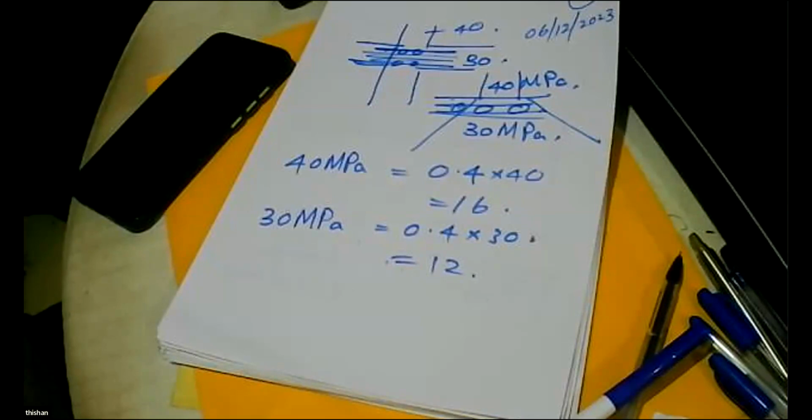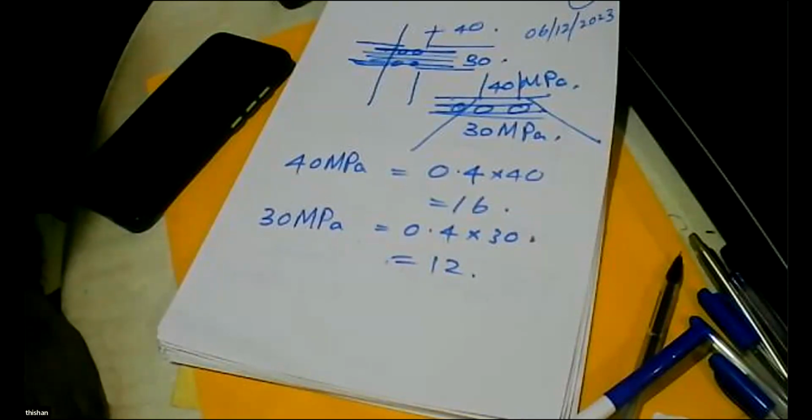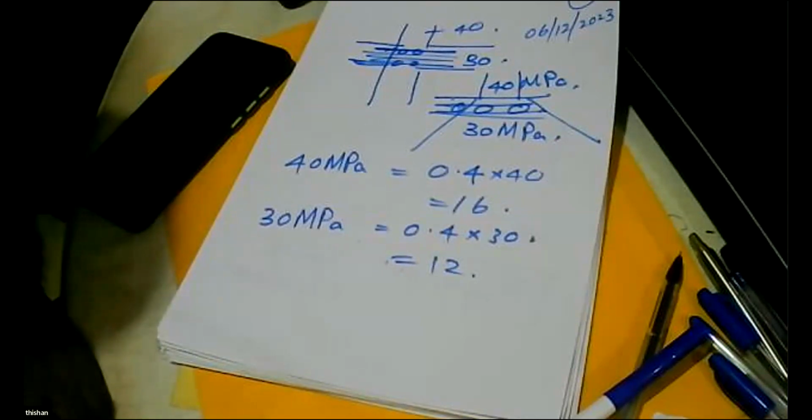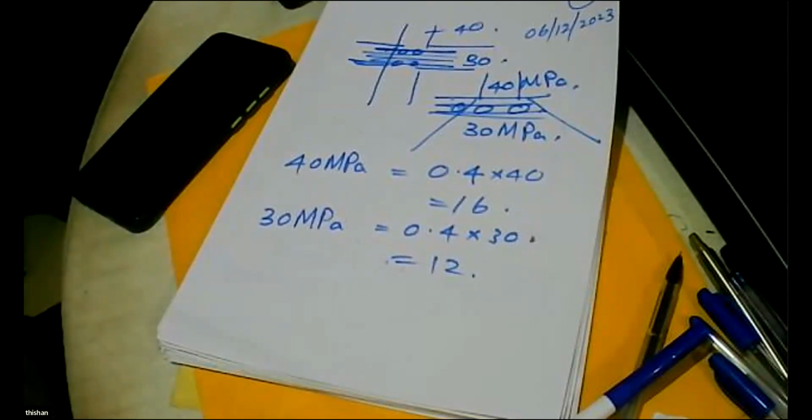You can do pile rafts only in areas having very good laterite soil, where the bedrock is deep and you stop the piles in the laterite soil as friction piles. Otherwise, if you have end bearing piles, going for a pile raft is wrong.